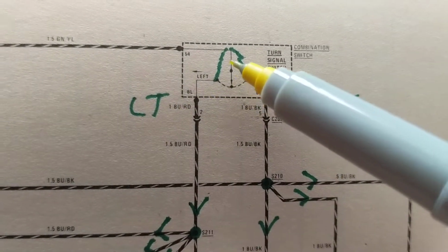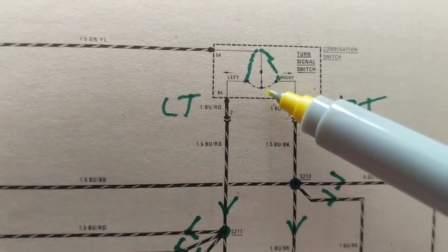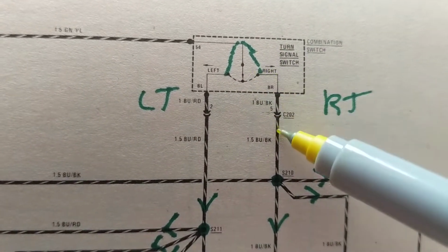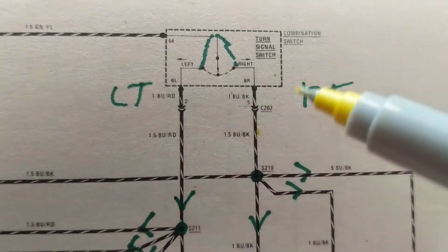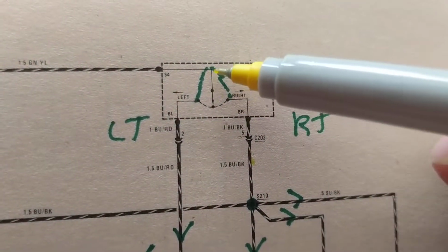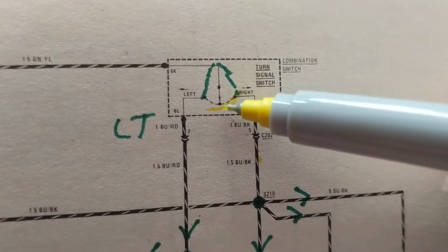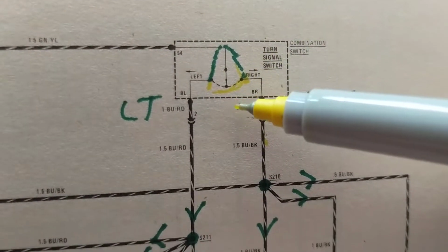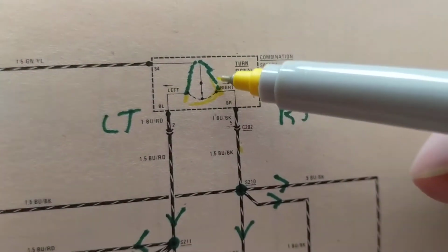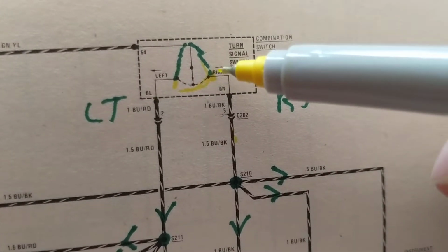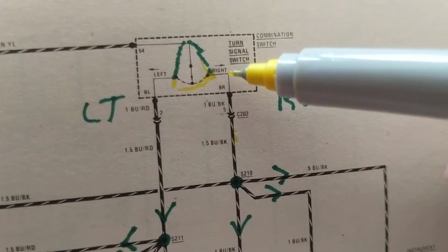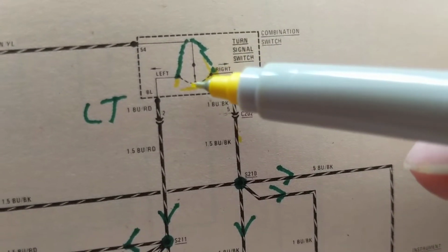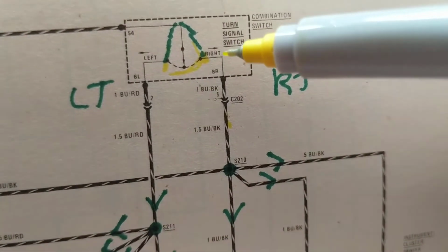and left this way. The switch has multiple points that it can make contact with. And therefore, the connections go to the points. So therefore, this is 3 points, a switch. As you can see, I put this one, this one. We know we have bulbs, right turn signal and left turn signal. In this way, this is right, when you turn on the switch. When you go the other way, you're turning on the left bulbs. We have rear, we have front, park.